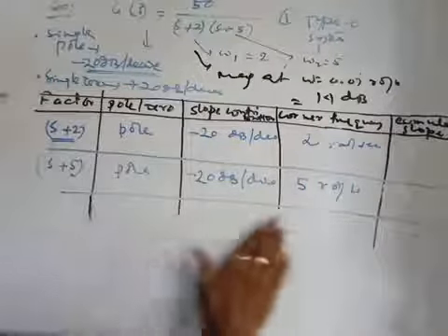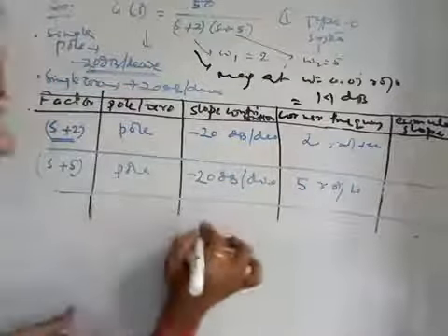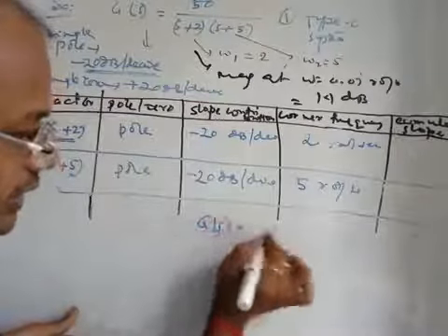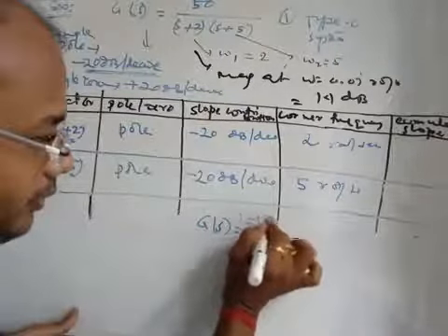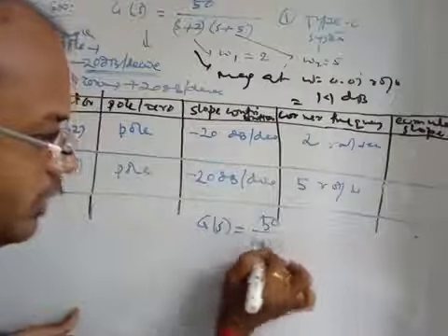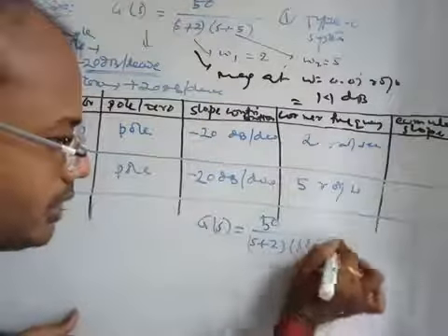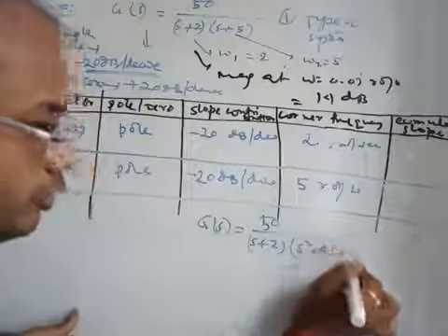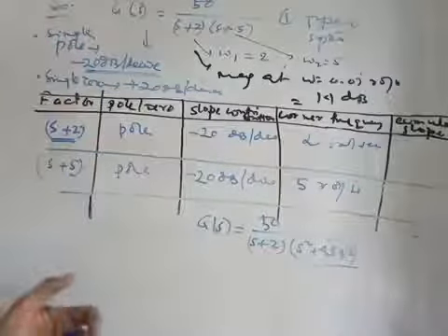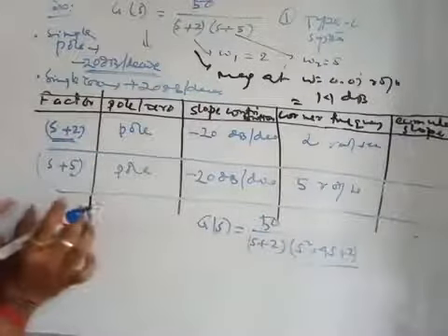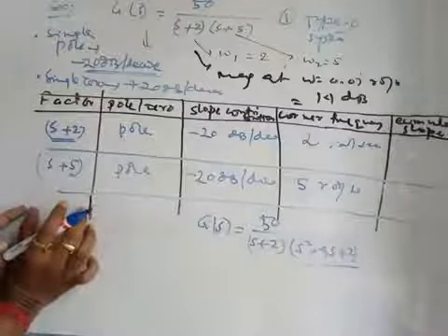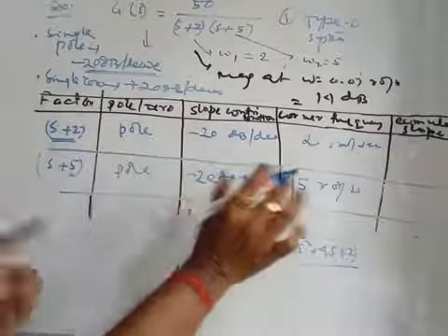And for example, if there is a second order factor, how will this look? For example, I will take the example later on, say 50 by s plus 2 into s square plus 4s plus 2. So this is the second order factor, right? In that case, you have to write the factor here, s square plus 4s plus 2. Corresponding to that, what is the corner frequency?